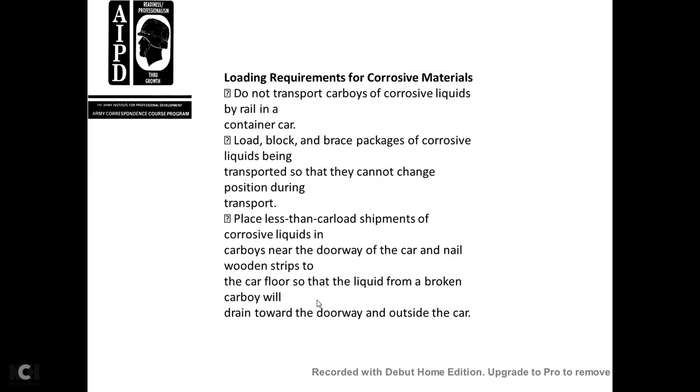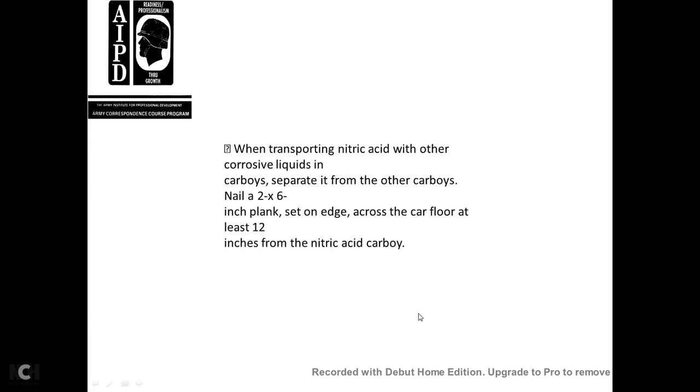Loading requirements for corrosive material. Do not transport carboys of corrosive liquids by rail or container car without loading, blocking, and bracing the packages of corrosive liquids so that they cannot be displaced during transportation. Place less than carload shipments of corrosive liquids in carboys near the doorway of the car. Nail wooden strips into the car floor so that liquid from a broken carboy will drain toward the doorway and outside of the car.